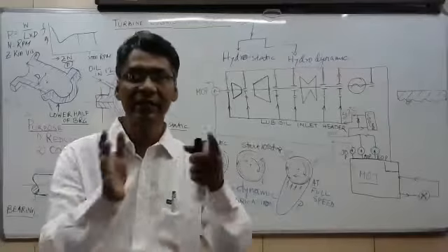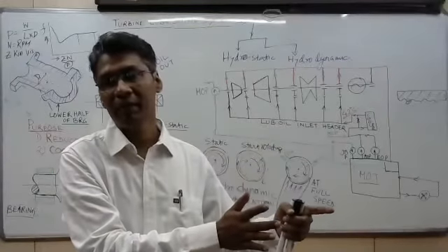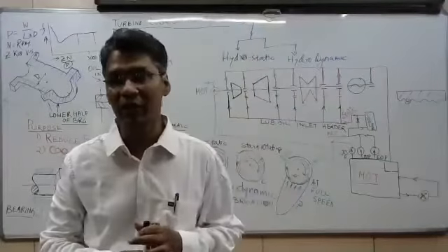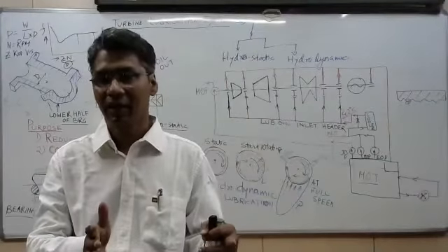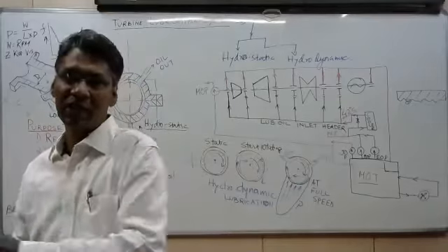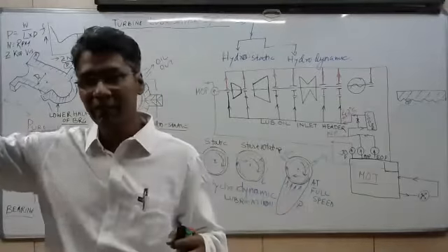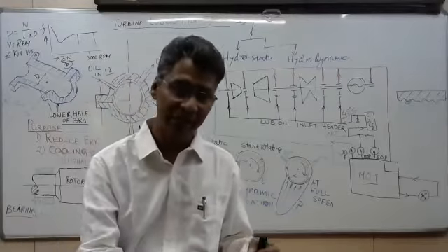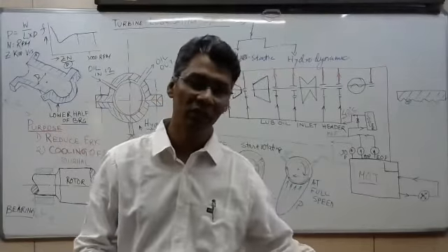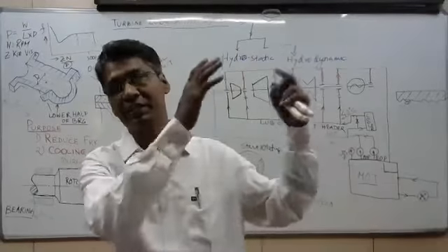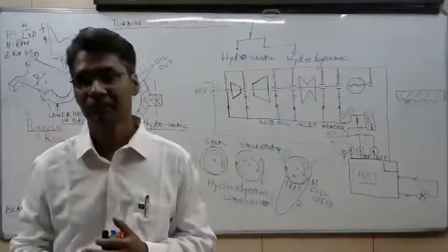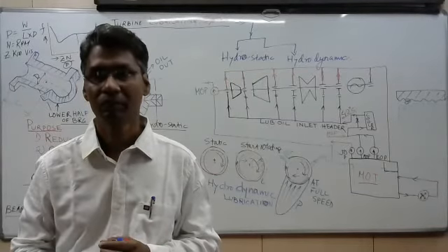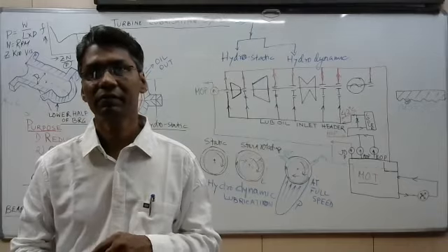By this way, we are getting better oil at the auxiliary pump section, where the pumping is done to transfer this oil. That's why the partition is given, because the dirty oil goes to the clean portion. After the partition, when the oil is delivered to the rear end, there are 2-3 partitions. By cleaning through the partitions, cleaner oil is deposited in the extreme end where the pumping is done. Next question. Any other questions?